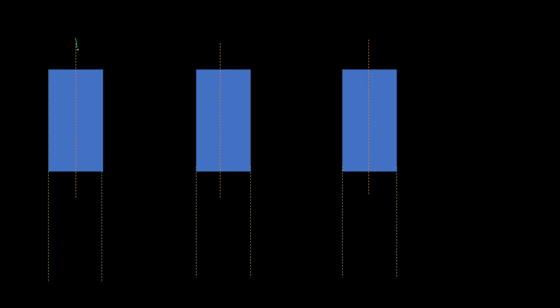So this is the last part of our analysis, that is the force is acting and a moment is acting. Now what we'll do, we'll try to analyze these two separately. That is, in the first case we will apply only the point load, that is the direct load on the member. So we are applying a direct load here, and in the second case we'll be analyzing only the moment.